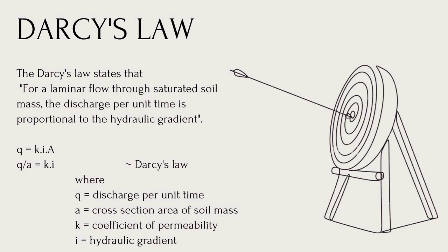Darcy's law states that the rate of fluid flow through a porous medium is proportional to the potential energy gradient within that fluid. The constant of proportionality is the Darcy's permeability of soil. It is a property of both the porous medium and the fluid moving through the porous medium. In fact, it is the empirical equivalent of the Navier-Stokes equation.